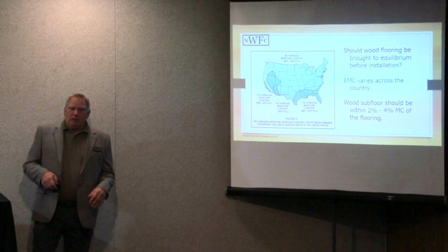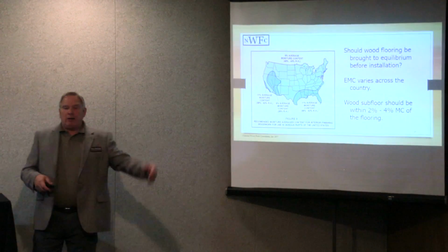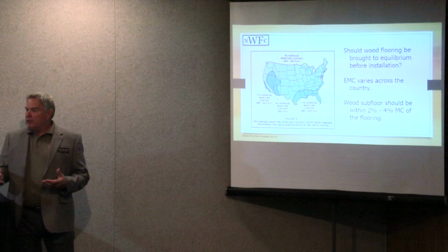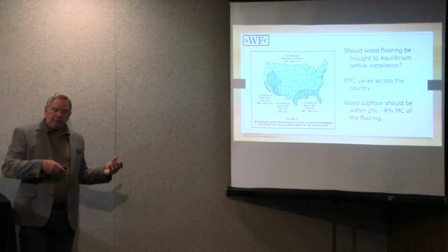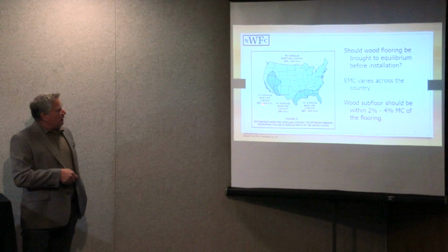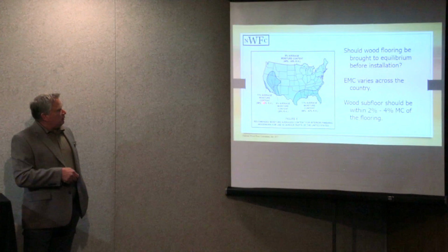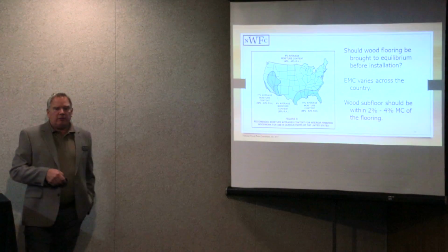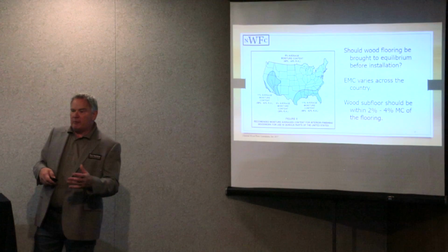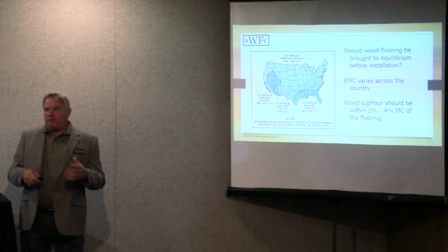So, my sister lives inland, but I want to have this floor. Well, those two floors are not going to perform equally in a microclimate like off of San Francisco. So 50 miles in, you're seeing that the average RH in there is around 63% with an 11% moisture content. So if we're dealing with a product that has a 35% requirement, we know we're guaranteed failure for that.